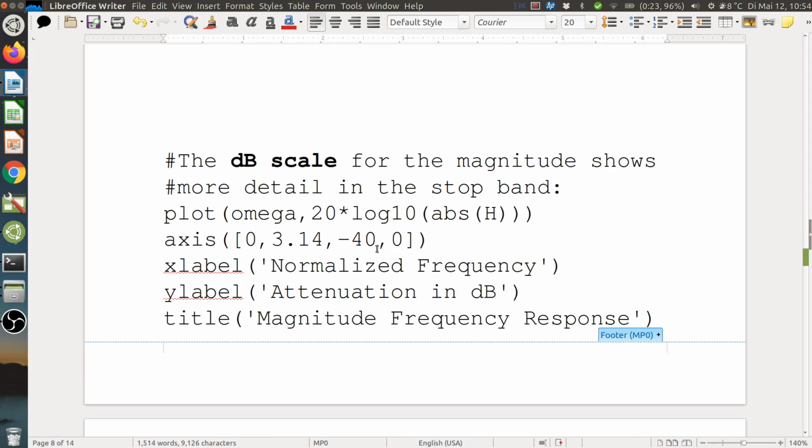Yeah, and especially for the attenuation, for the small values, the dB scale is very practical because it shows the magnitude in more detail for small values, because the dB means we apply the logarithm, right? And the logarithm means we see small values better. So here we can see that we apply the log for voltages or currents with a factor of 20.